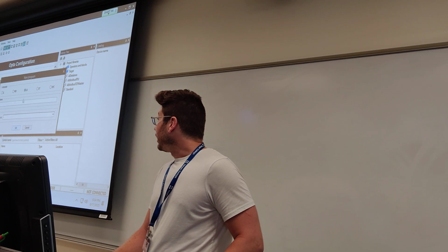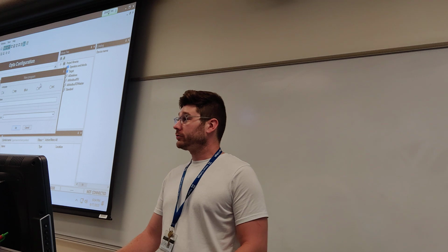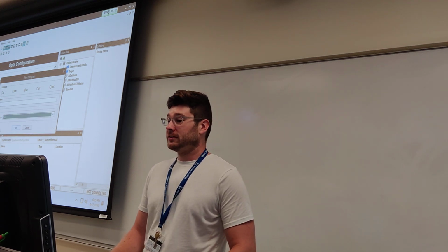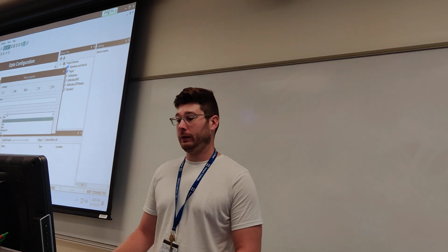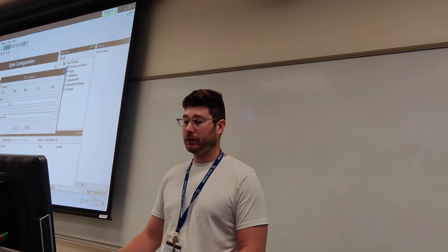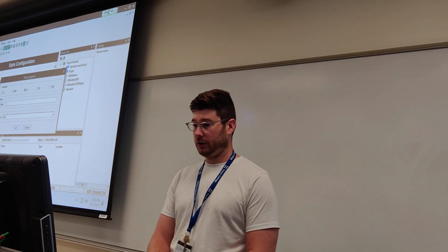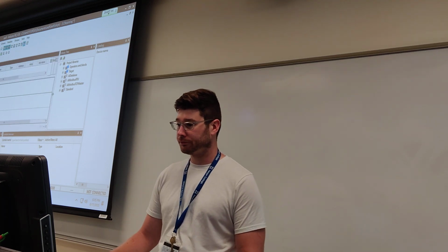We want ladder diagram for this particular programming language, as opposed to structured text, which is what we used before. Again, it's very important that we assign it to the fast task group so it will actually run. If you misclick and put it on the slow or the background task, it'll just run slower. But we want the fast task group, and we'll call it LD learning. You can call it whatever you want, it's just for us humans.